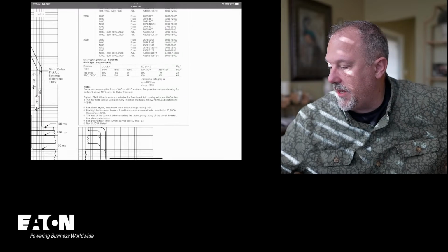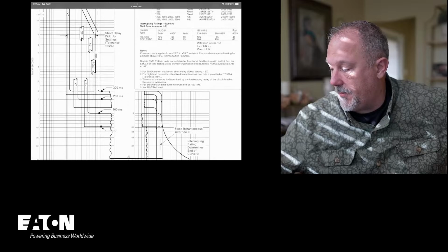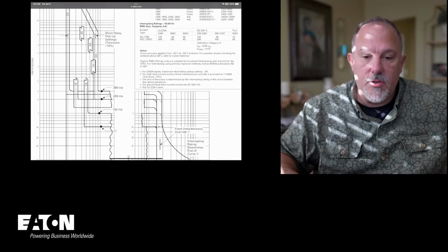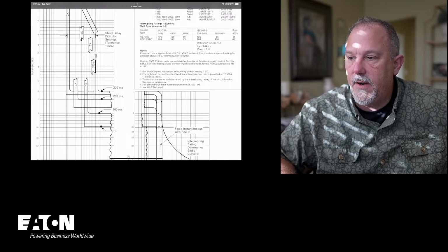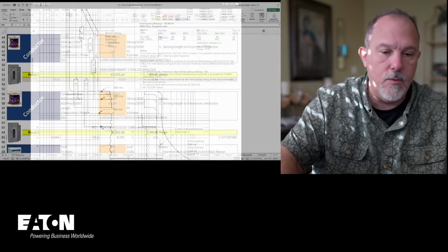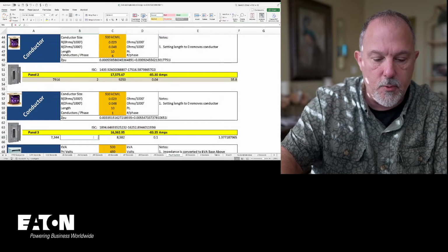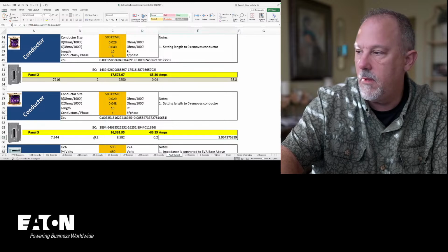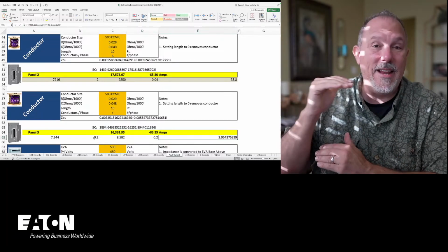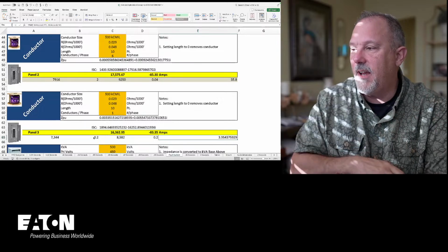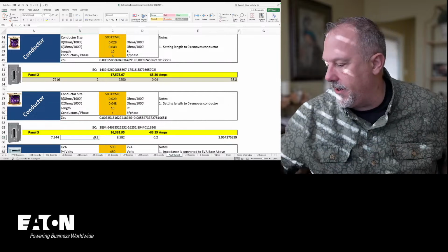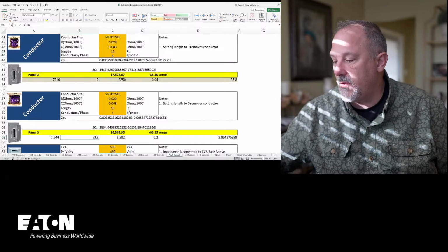If my short time pickup is at 200 milliseconds, so that's 0.2 seconds, I'm going to change this to 0.2 clearing time. I'm at 4 calories. Much better than 35.8, okay? I'm at 3.9. That's at 0.2, but I want to go better.